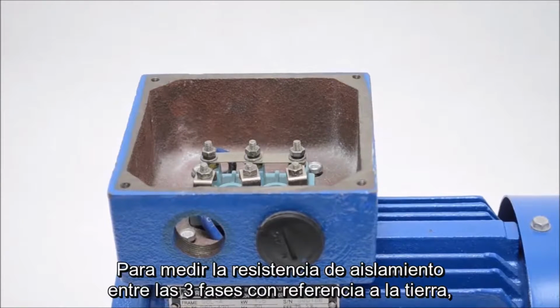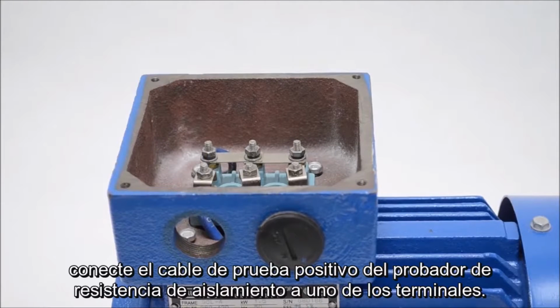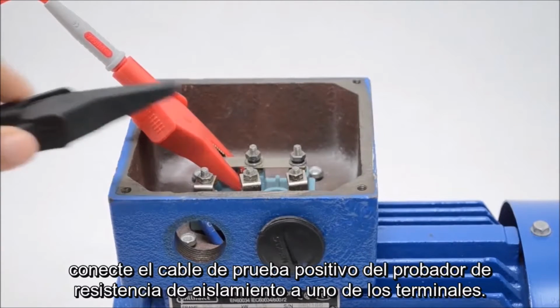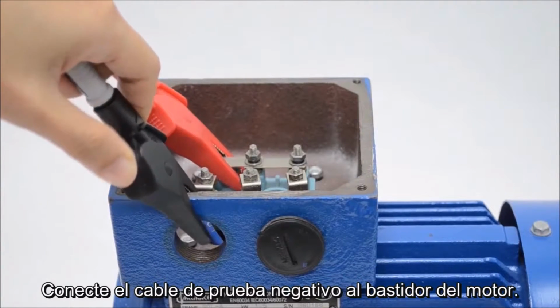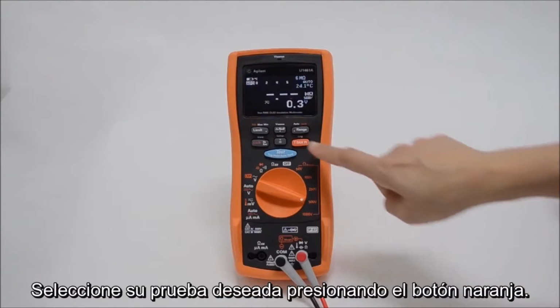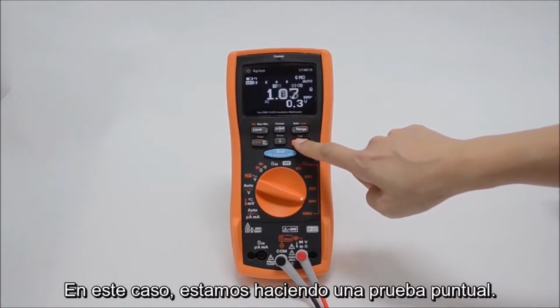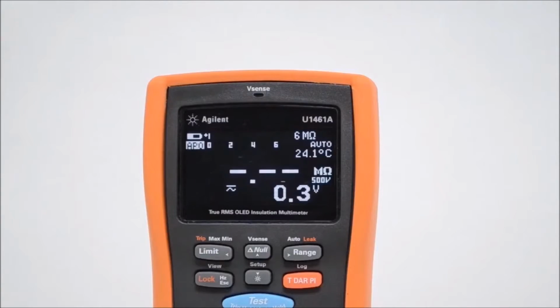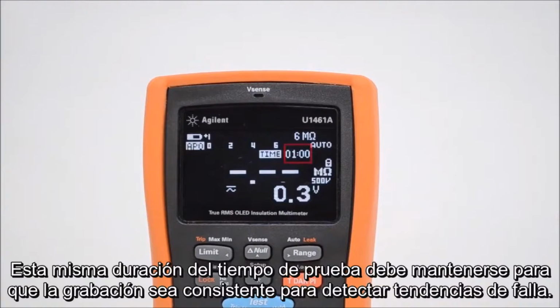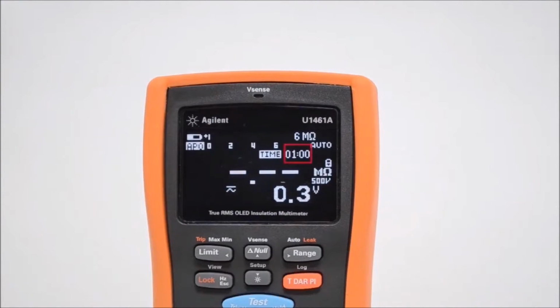To measure insulation resistance between all three phases with reference to ground, connect the positive test lead of the insulation resistance tester to one of the terminal leads. Connect the negative test lead to the motor frame. Select your desired test by pressing the orange button. In this case, we are doing a spot test. Use the appropriate test time to obtain the insulation resistance measurement. These same test time durations must be maintained for consistent recording to detect failure trends.